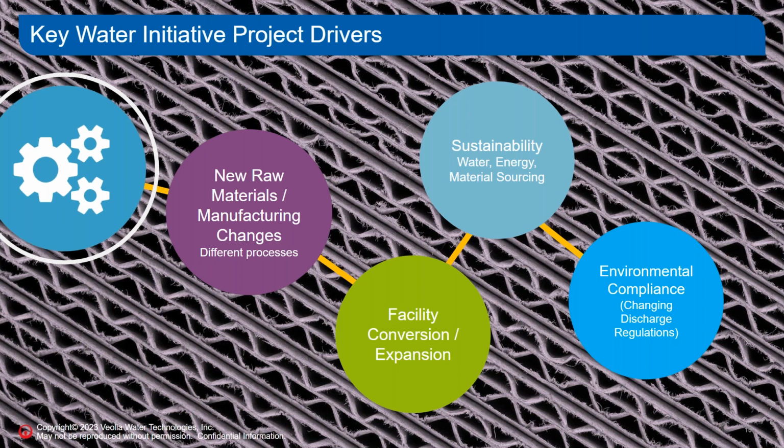Paper fibers, on average, are recycled 5 to 6 times, with 20% of the fibers being lost in processing due to reduction in fiber length and strength during cleaning and refining processes. Pulp and paper mills have had to be converted and upgraded to be able to use and process a combination of all these different types of recycled paper in combination with virgin pulp.